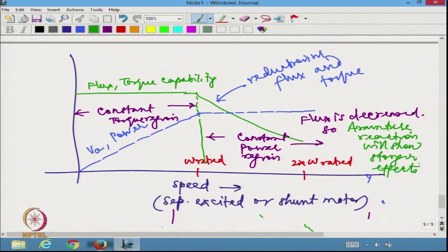So, you may see that the torque actually decreases more than what we anticipate it to decrease, because armature reaction is going to decrease the flux further and further as it is. Let us say this is 100% flux, maybe some 0.5 Weber. At this point it will be 0.25 Weber. So, very clearly compared to 0.5 Weber, maybe armature reaction was having a reduction of 0.1 Weber, it would have become 0.4 Weber here, but here it will become 0.15. So, 0.15 becomes extremely small, because of which it may not be able to develop enough torque at the end of this, right.